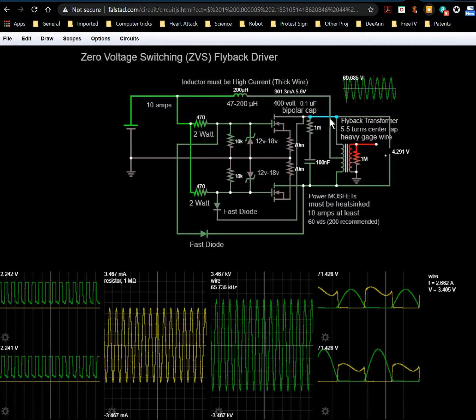But really, we are talking about the voltage here and here, because the important thing to remember is that this capacitor and inductor are actually playing off each other. When you see this approach 0, it is actually 0 volts across both of these components. But the current tends to be maximum. In other words, at that point, the capacitor's current is changing at its maximum rate, trying to charge up the inductor, or vice versa, depending on how this thing's going.